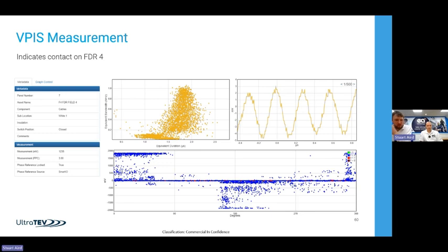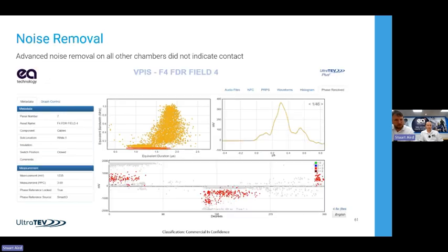We can see here there are bits of this that look like PD, but the waveform would not give you any confidence of that. A lot of these waveforms are noise. You've got a lot of background noise going on. What we can now do with our tool sets, or our service teams that will be using them in the background, is filter that noise. We can look at what the energy and the waveforms look like in certain parts of that activity.